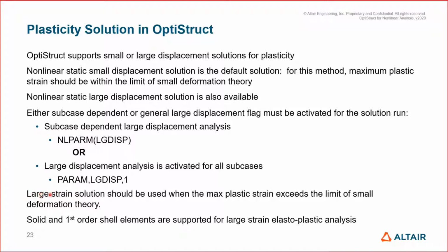The large strain solution is always turned on when our plastic strain exceeds the small strain deformation theory. So when the plastic strain in your model exceeds 5 to 10%, we will turn on the large strain solution automatically. Okay, so don't worry about that.